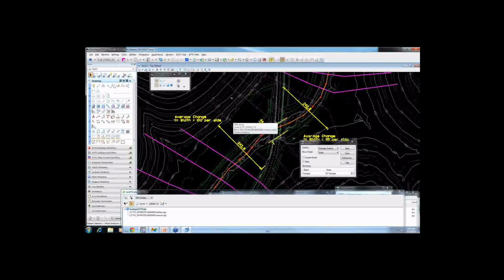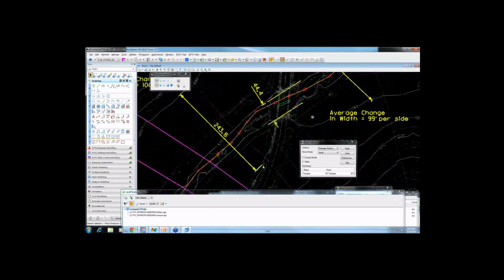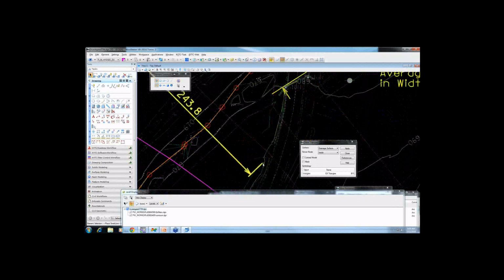Do it again. So it can take a couple iterations, but what I do is go to where I think the contraction length is going to hit and measure the floodplain. So here I said from about 680 to the roadway fill is probably how wide it's going to be.